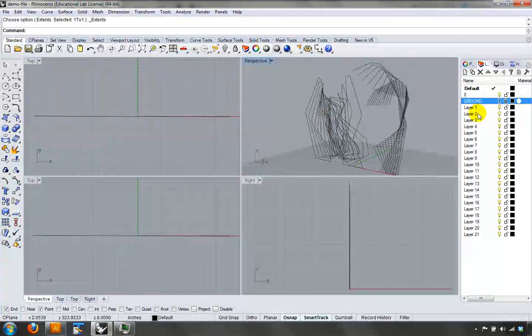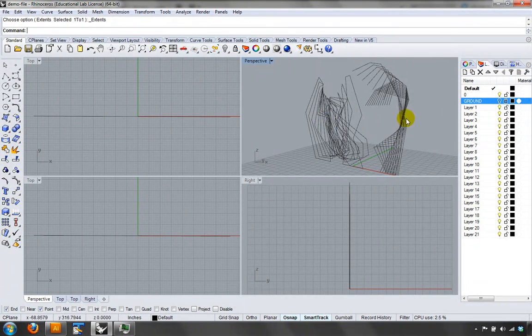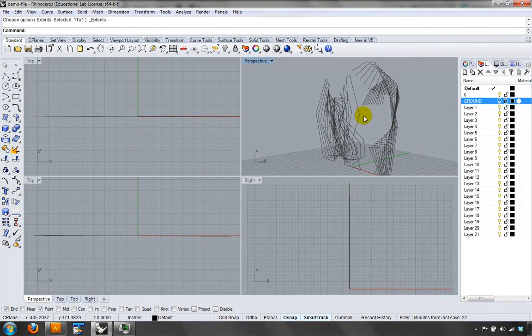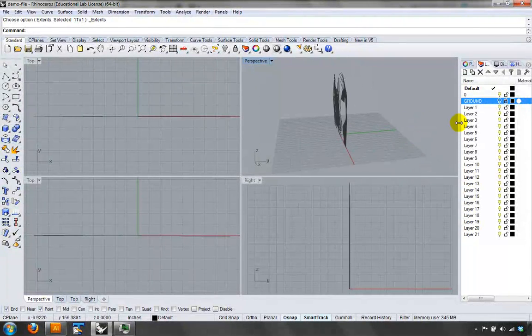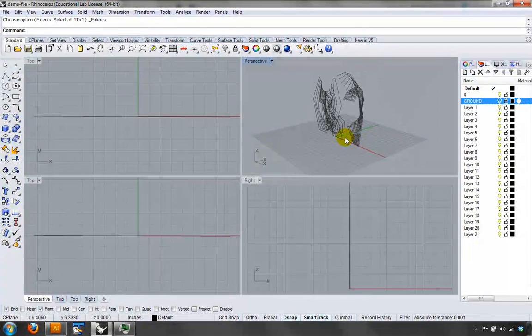They're rotated, they're scaled, we're good to go. Okay. Now the next part is going to be to move these things into position so that we can loft them as sections, right? They're all stacked on top of each other. They don't have any, in this case, Y depth. You can see the sort of axes here. Z is up. X is headed this direction, and Y is headed in a depth here.